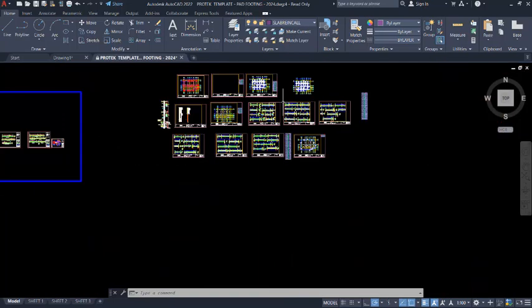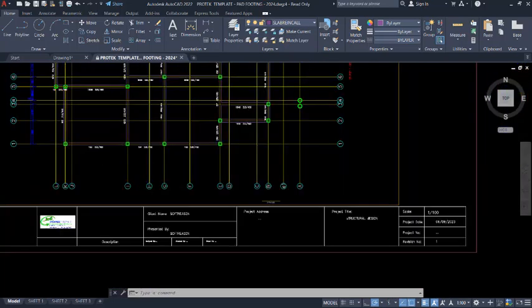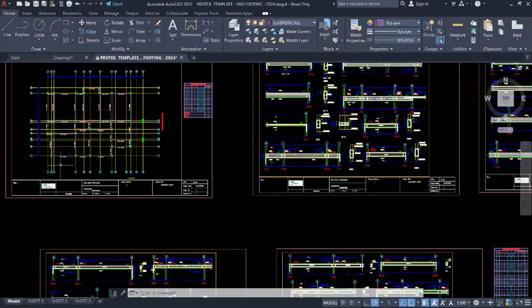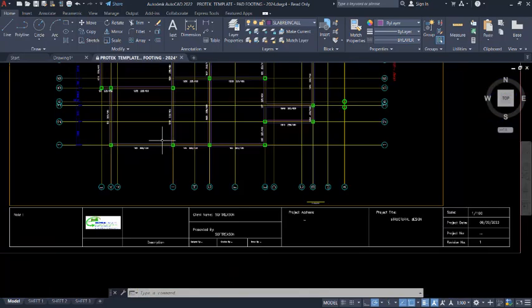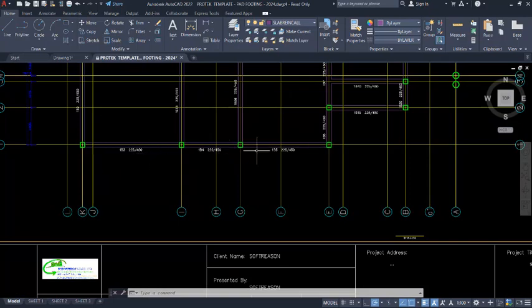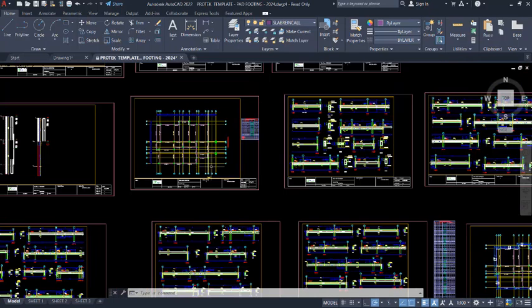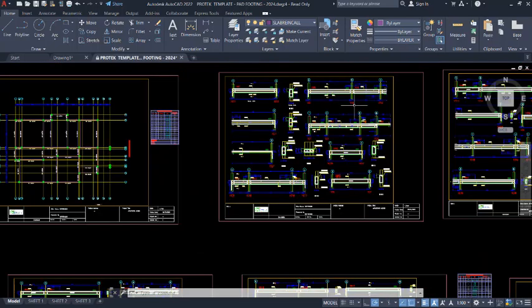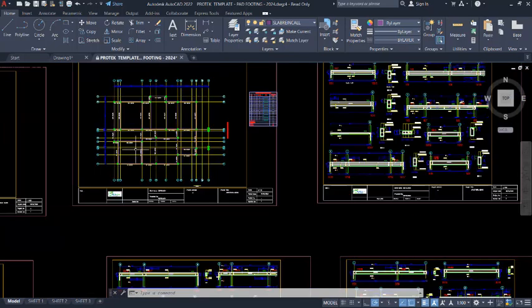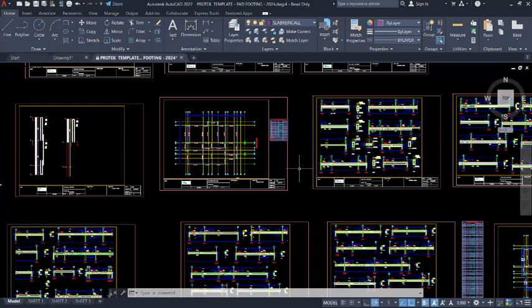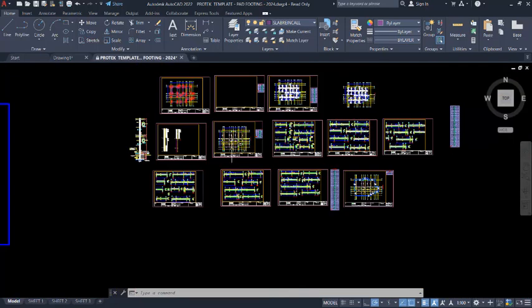So if now you want to make this beam continuous, you will need to locate the beam over here. As you change the name here, you can call it first floor beam 1 right here, and then locate this same beam with this name right there and change it to first floor beam 1. That's all. So you do the same thing to all of the beams. Okay, for a proper and standard presentation. Okay, I believe this is understood.